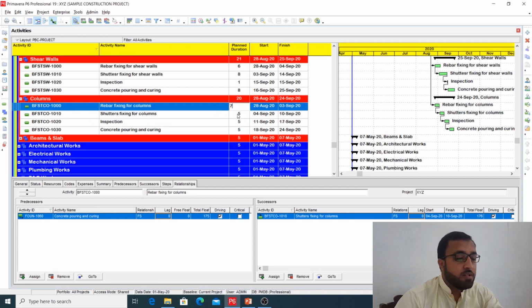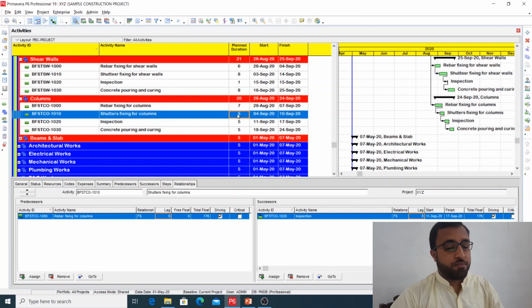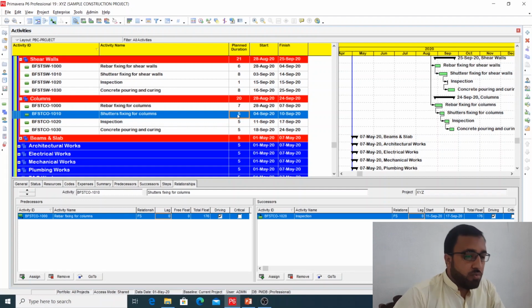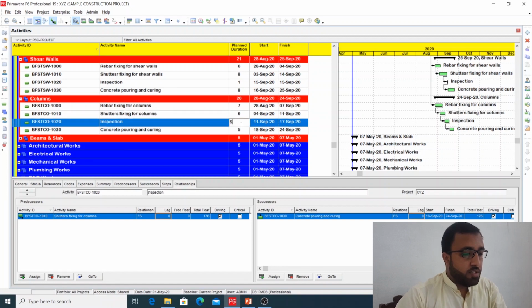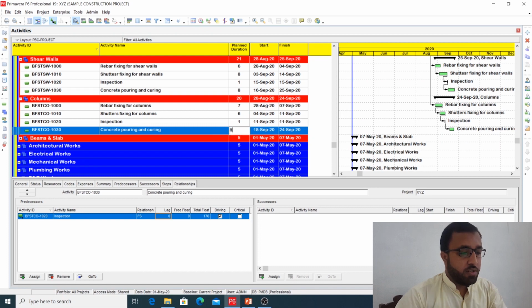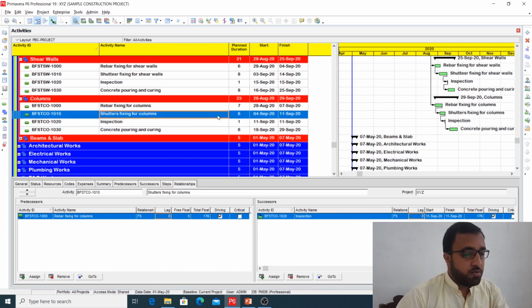Here I am giving durations randomly, but you need to give them based on the productivity and the quantities. I have already spoken about this. Inspection will take only 1 day, then concrete pouring and curing, okay, 28 days. So here you need to connect with start to start plus 3 days.